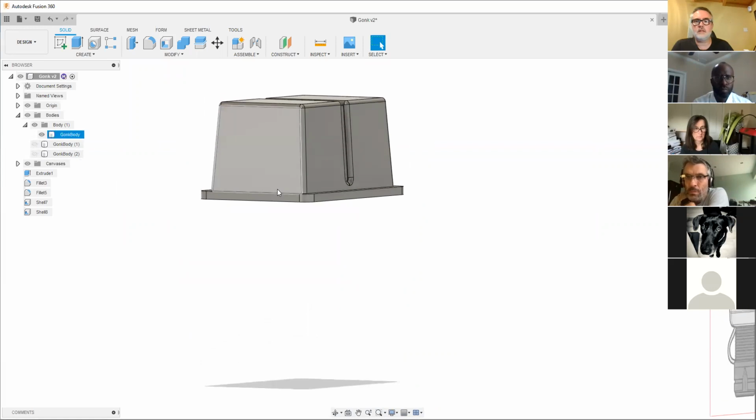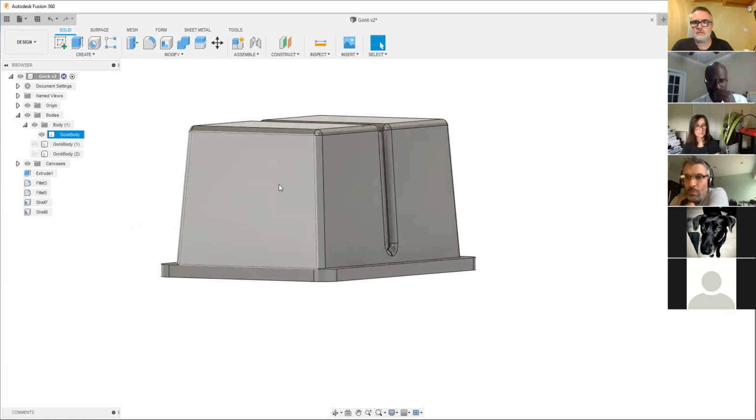Is a 3 millimeter thickness a typical thickness that you use for most of your stuff, Michael, or does it just vary depending on the object? It varies depending on the object, depending on the strength that you want and what you're actually going to put through it. Because this is a fairly small model, I think they scaled it at the Hot Toys sort of scale. 3 mil will be fine. On domes I use 6 mil, just because the skins of R2 and whatever, 6 mil gives you a good solid body. But sometimes, like the Sandcrawler, I might want to put bolts through to allow me to bolt 2 pieces together, so I might do 7 or 8 mil depending on the thickness. Well, typically 6 mil is my go-to on the big stuff and 3 mil on the small stuff.